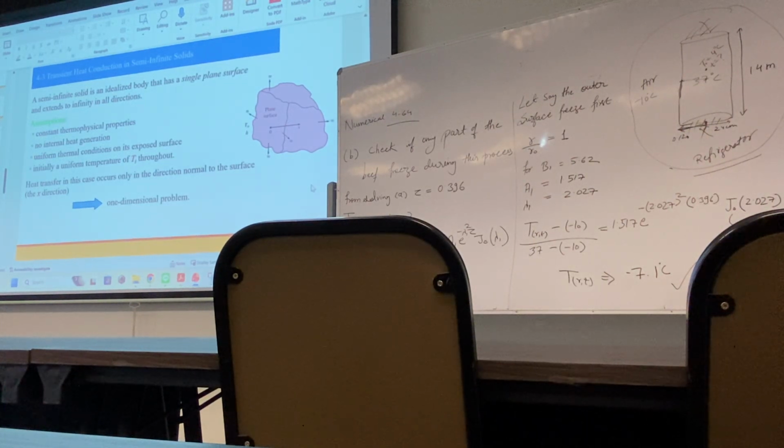again, like if there is a pipe buried inside the earth, and it is buried only a few meters from the surface of the earth. So in that case, in the z direction, the distance is infinity in comparison to the few meters that the pipe is buried. So in that case, this is a semi-infinite solid plane. Okay, so earth, laser treatment, anything that is very large in comparison to where you are studying the heat transfer can be assumed as a semi-infinite solid.